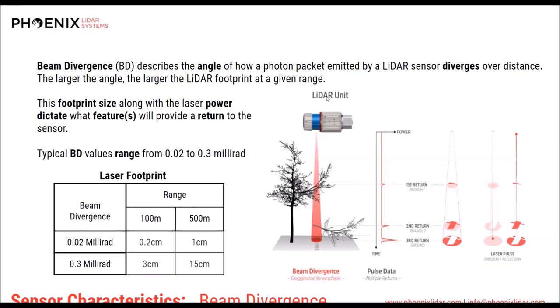No, actually, I think you hit it perfectly. I think the HA is unbelievably perfect for mobile applications, but has some significant limitations for UAV applications. I wouldn't want to have its returns go much further than 60, 80, 100 meters. And at that point, putting that unit up in the air, the return on investment isn't necessarily there if you think about the VUX HA as a UAV-centric sensor.